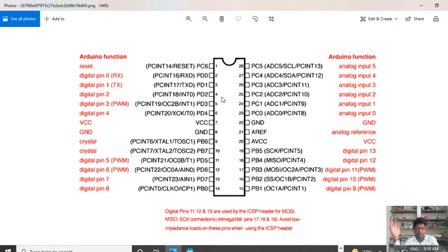It will be much safer, through some external hardware circuit with dead time generation. So we need to know how the dead time should be generated. Normally, if you see any driver, only one actual pulse you need to give, and the dead time setting will be in the driver card.